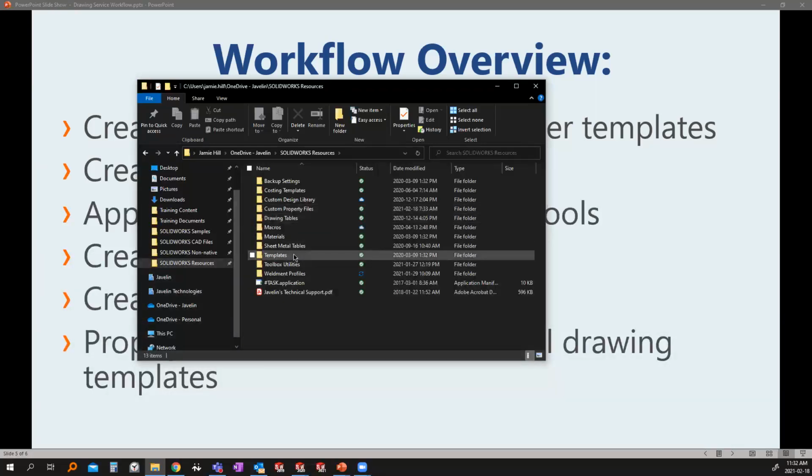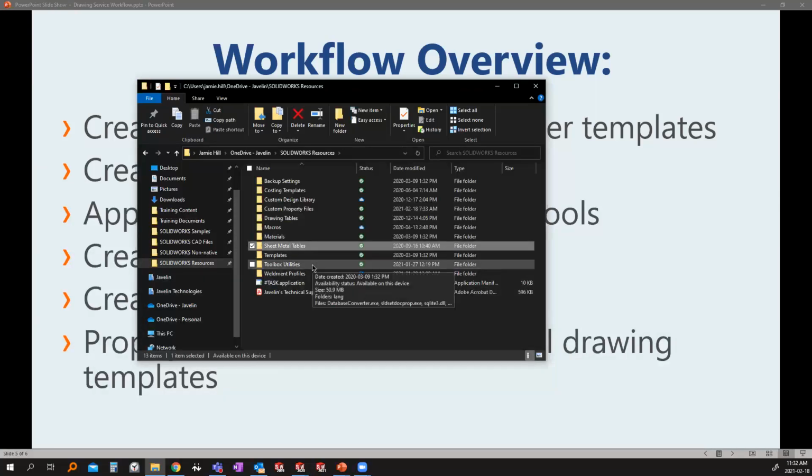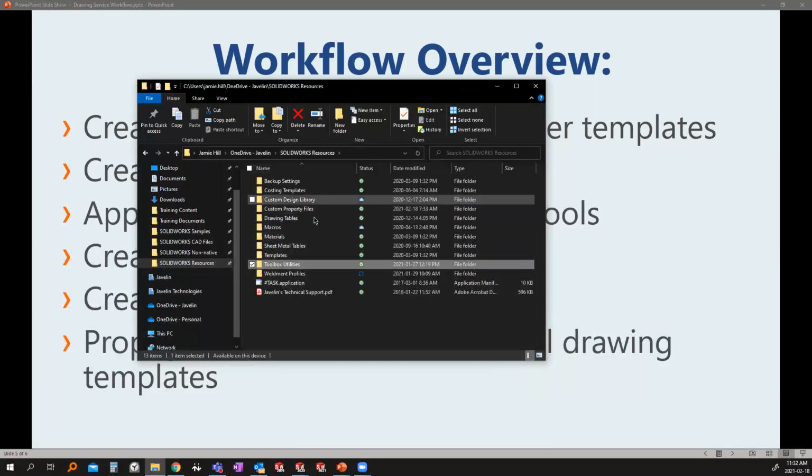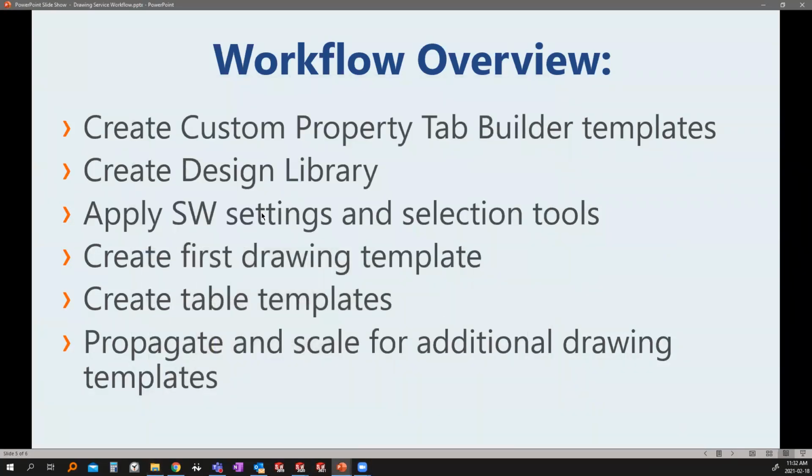You can see I have a number of different things here, from material libraries to sheet metal gauge tables and bend tables to profiles, toolbox. Everything that I've tailored in SOLIDWORKS, I stick in one administration folder, specifically outside of the installation directory. That way I ensure if I, say, uninstall SOLIDWORKS one day, that I don't lose all my hard work. So in your settings, you can just point your file locations to those folders.